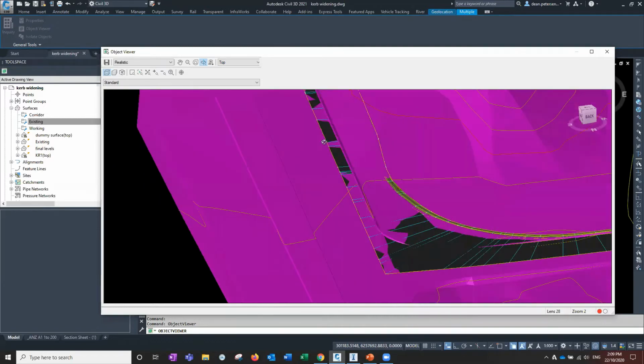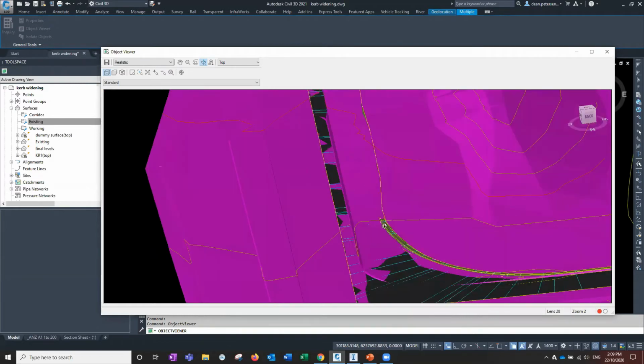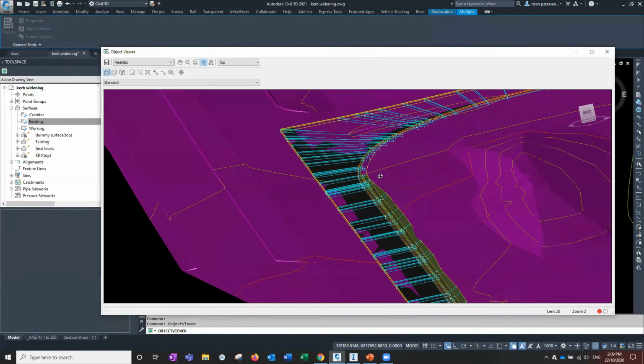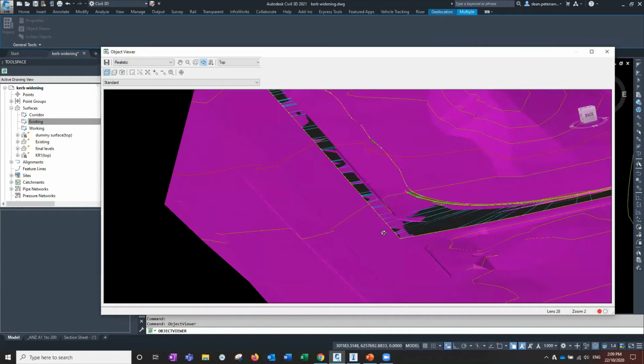So you can see they're running a shortcut line out in the road and then projecting back to the curb. The curb is above the existing ground here, and if we go underneath, we'll see it's below the existing ground at that point and got better slopes coming up. So that's looking good to me. So there's all those little checks you can do. And you can pick, obviously, whatever elements you actually want to pick in there. For instance, there is these pipe networks here as well.